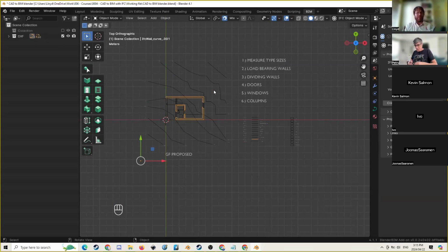I'm going to basically draw this natively in Blender BIM instead of holding the DXF information, because the DXF information is actually heavier inside of an IFC than a 3D model is, which we'll see. I'll show you how to convert it into an IFC annotation so it can be saved, but that'll be a little bit further down the line, probably in 30 minutes or so, essentially.